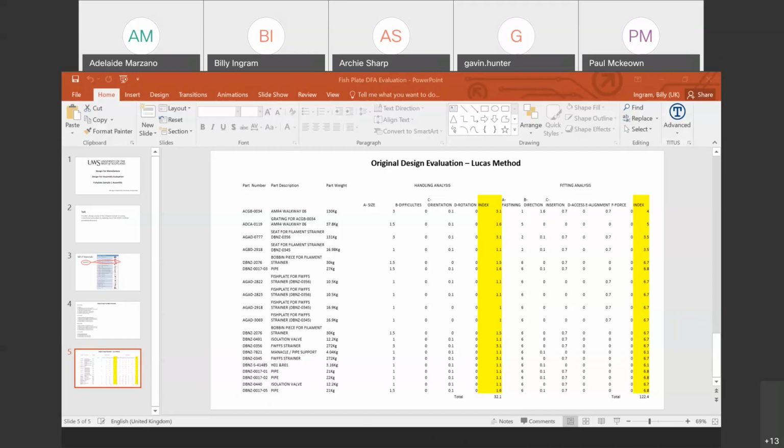Okay. So what do you mean with the shimming? With a green material? Rather than having green material on it, we just make it to the smallest nominal size, and then it's fully assembled in the shop. And when you have to take up any spacing, basically lift the fish plate up to align with the holes, we just use a pre-manufactured shim plate for that at 1 mil, half a mil to take up.